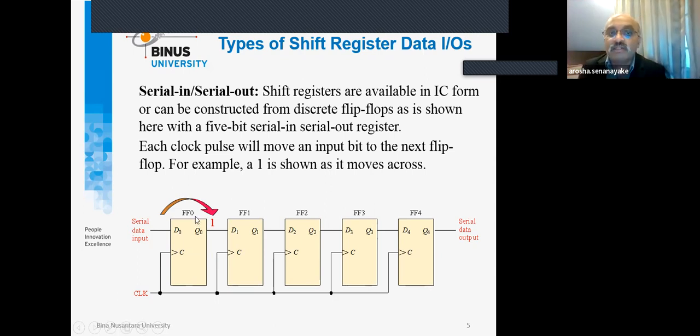So then likewise, this can be shifted. So at each and every clock pulse, one bit is moved. One D-type flip-flop really will be activated and then moved one to the next or subsequent D-type flip-flop. So when it receives another clock pulse, then it receives, so then it sends, and another clock pulse, that one will be out of the serial register. So then we have 1, 2, 3, 4, 5.